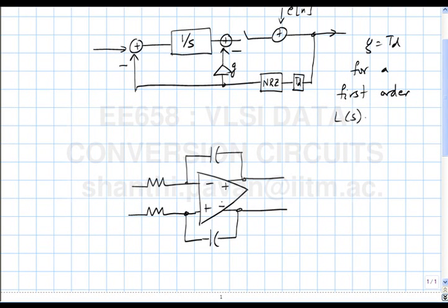So in this differential op-amp, the difference in the output voltages is a large multiple of the difference between the input voltages. And I guess all of you have also taken other classes or are taking analog IC design. In any case, in this course early on, I explained the need for common mode feedback in all these fully differential structures. So this is the integrator.